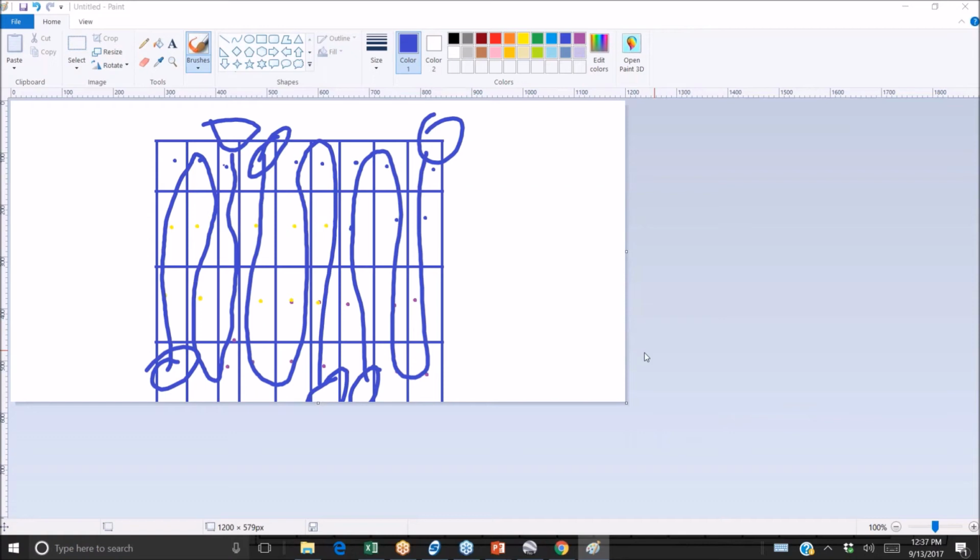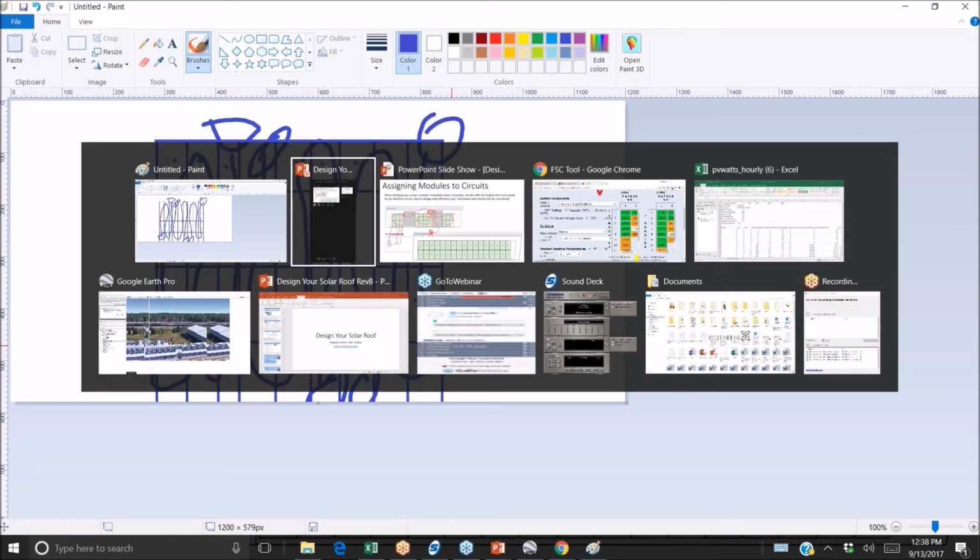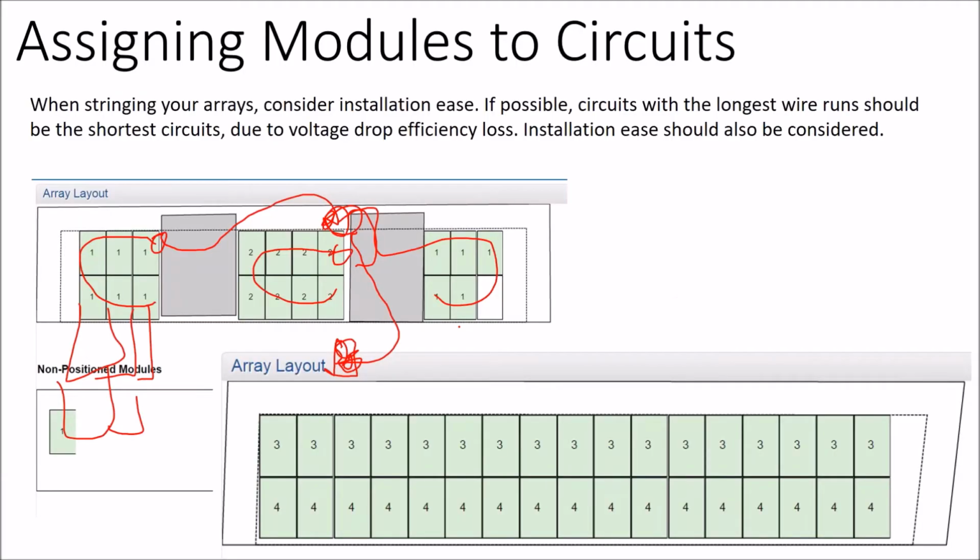Nowadays with cheaper modules, you can do larger systems, but with these module level electronics, the maintenance issues come into play. Now you don't have that Solar Pro making every single connector, but a lot of new installers doing this stuff for the first time. Maybe you have non-electricians making those connectors, and it's just better to locate them at the edge. Let's get back into our solar array.